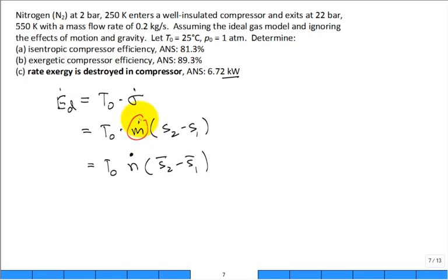So what is the M dot? Well, that's a mass flow rate. What is the N dot? Molar flow rate. How do I move back and forth between them? Use the molar mass. Yeah, the molar mass. And so what was our molar mass? 28.01 on the nitrogen, true? What are the units on this molar mass? Kilograms per kilomole. And so you just use that all the time.